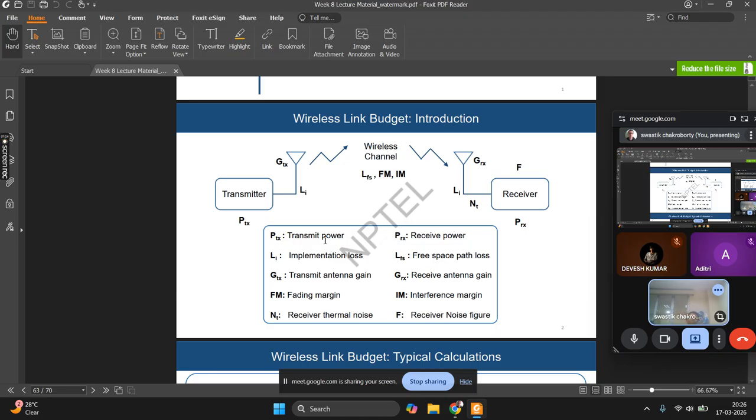you have transmitted. Now, a receiver has something called a sensitivity, receiver sensitivity. So if the power level it receives finally, after all the additions and subtractions, is lower than that particular dB of sensitivity, then it basically detects noise. So each receiver has something called a signal or noise detection, a Neyman Pearson detector. That Neyman Pearson detector has a particular threshold. If it crosses that threshold, then it is a signal. If it does not cross that threshold, it is noise.